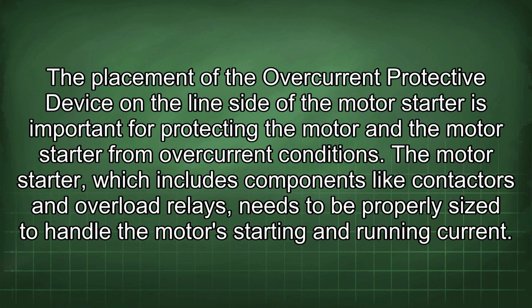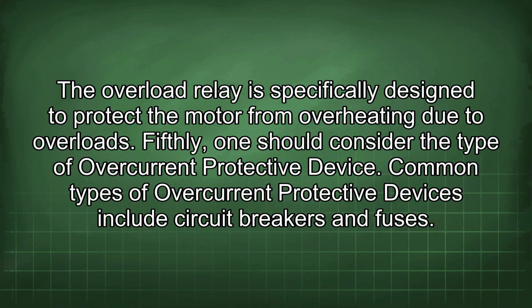The placement of the overcurrent protective device on the line side of the motor starter is important for protecting the motor and the motor starter from overcurrent conditions. The motor starter, which includes components like contactors and overload relays, needs to be properly sized to handle the motor's starting and running current. The overload relay is specifically designed to protect the motor from overheating due to overloads.